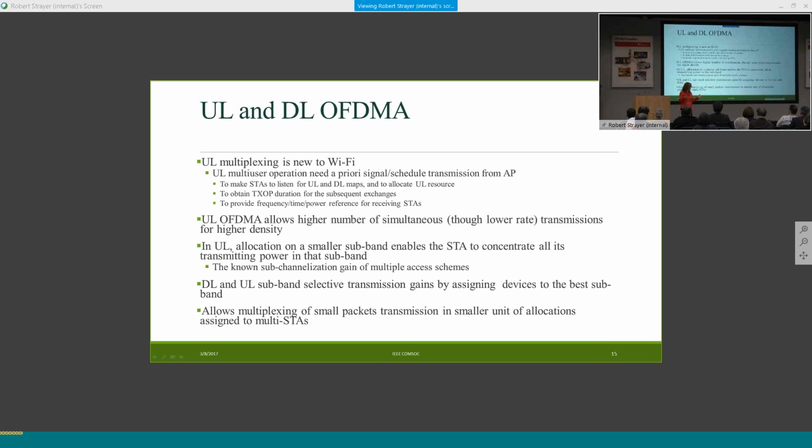There is no nudge or something. So it's really time constrained. Same thing here. In the trigger frame, 16 microseconds after the trigger frame, the stations transmit back, like stations A, B, C in OFDMA fashion or multi-user MIMO fashion. This 16 microseconds is a very hard constraint for the implementation of the devices to turn around, decode the packet, and figure out what they need to transmit next.